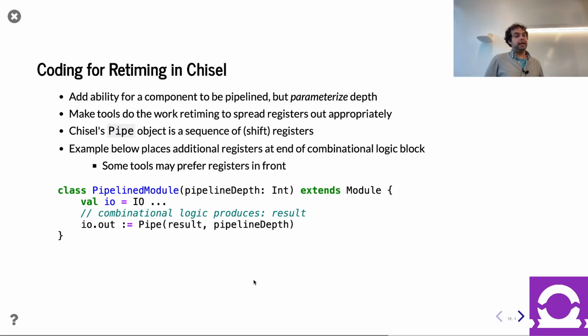The FPGA tool still can do some retiming. It's just very local what they can do. So basically, we have code where every place a register might be able to go, we have some sort of annotation. And then there's still a parameter, once again, trying to maintain the complexity reduction. So I want to have only 4 registers in this design. Let's say that particular annotation occurs 8 times in the design. So somehow you need to prioritize which of those annotations get the register, and which of those ones do not get an annotation, or just pass through.